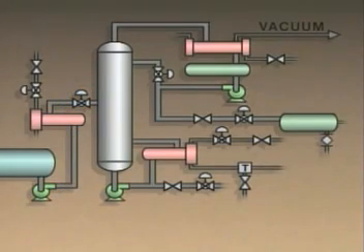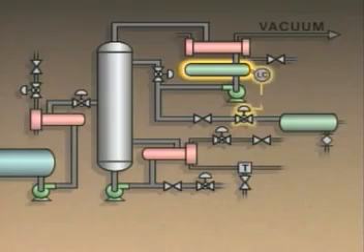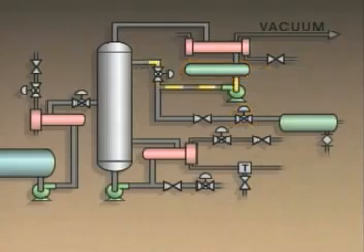With the flow of feed mixture to the column stopped, the level of overhead product in the receiver drops. When the level drops past a specified point, a level controller on the receiver automatically closes the overhead product takeoff valve. This places the system on total reflux.